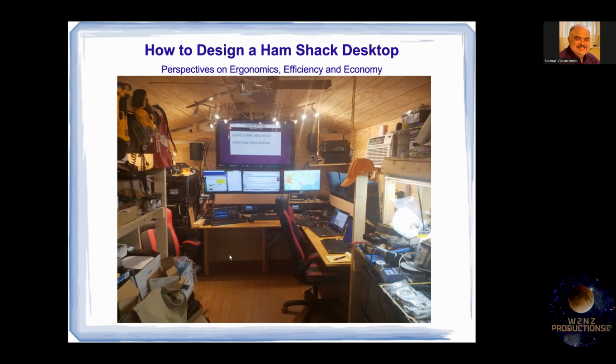Yeah, Gordon, I have a quick question. Yes, sir. Where are your grounds and where do they come into the shack? That's a great question. So this picture is a little old. There are several grounds. So around the building, there is what I call a ring ground. It's a piece of number 4 wire bonded to a bunch of 8-foot ground rods spaced every 6 to 7 feet, actually, going all the way around this structure.